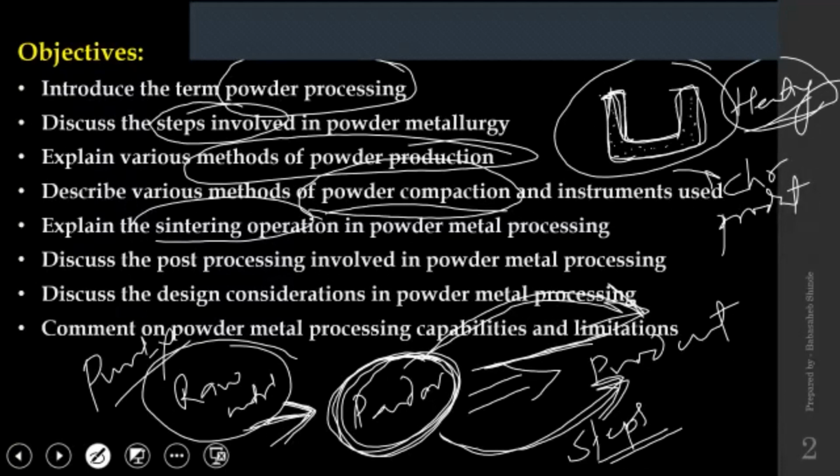So the next step is going to be a sintering operation. When you heat it at that elevated temperature, whatever binding materials that you have mixed in these raw powders will form bonds with the metal powders, and you will get the final characteristics of the product. Whatever final strength we are expecting from the product will be available after the sintering operation.